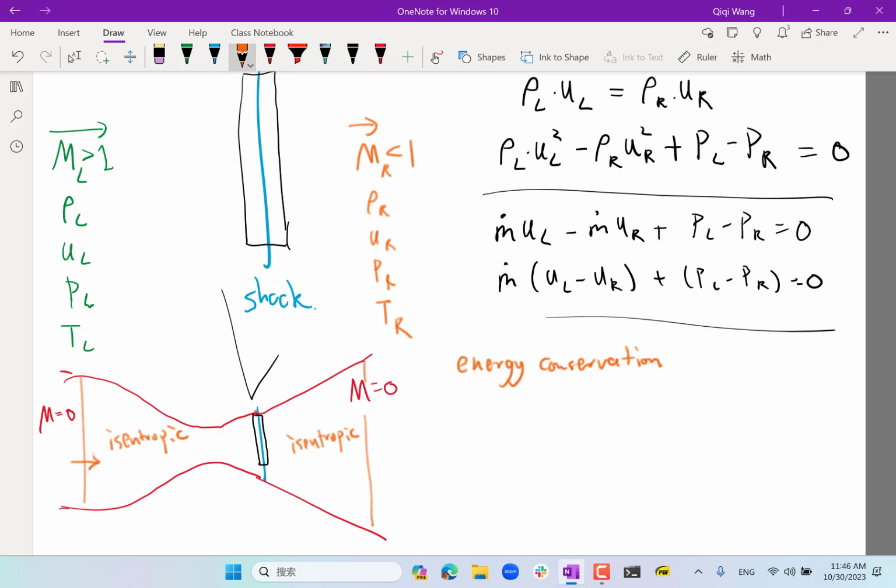But when you calculate the energy flux, let me just write m dot times Cv times T, where here we have T naught and here we have T exit. Cv times T naught is the flux of internal energy into the control volume, minus the same m dot, the mass flux, times Cv times T exit. So that's how much the energy flux has been in balance. That is a term that tries to increase the amount of energy in the system, all right?